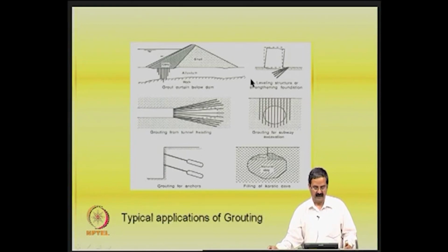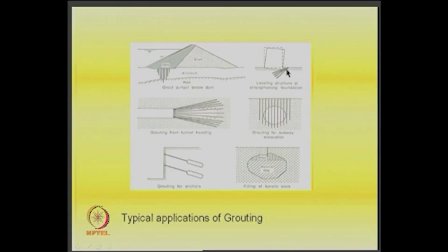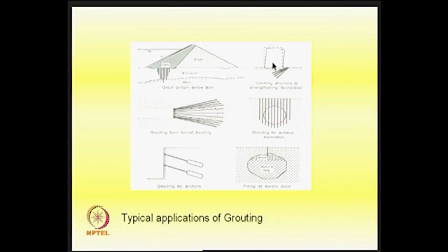Then the other one is leveling structures or strengthening foundations. So, for example, there is a possibility that foundation tilt is there. So, you would like to stabilize it. So, put some sort of grout injections into the system, so that it does not get damaged further.